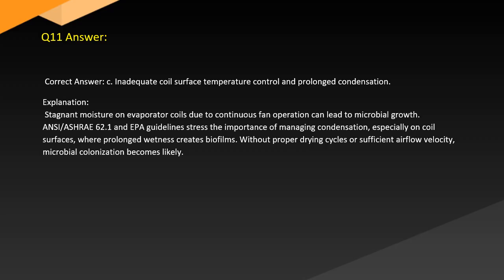Explanation. Stagnant moisture on evaporator coils due to continuous fan operation can lead to microbial growth. ASHRAE 62.1 and EPA guidelines stress the importance of managing condensation, especially on coil surfaces where prolonged wetness creates biofilms. Without proper drying cycles or sufficient airflow velocity, microbial colonization becomes likely.